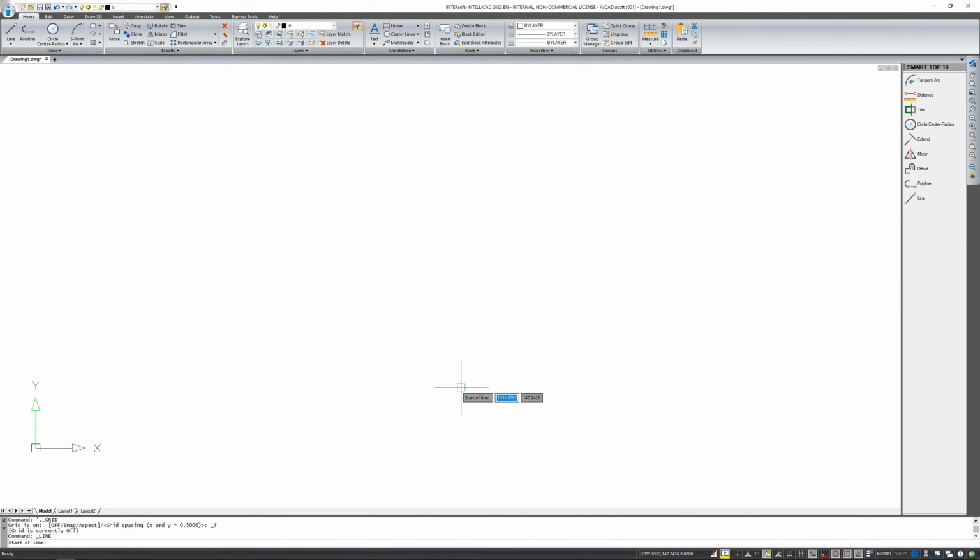You can enter absolute coordinates in the Cartesian coordinate system, that is x and y. You can enter relative coordinates, that is from the point where you last drew. And you can enter relatively but polarly, that is adding, for example, lengths and angles, not just x and y. If you have this box at the cursor enabled, input is relative.